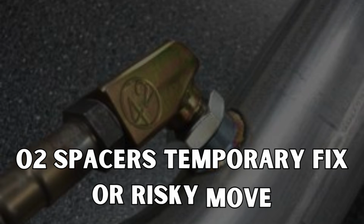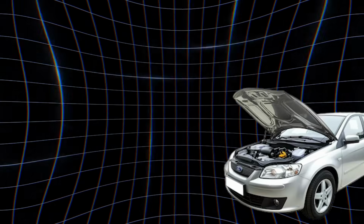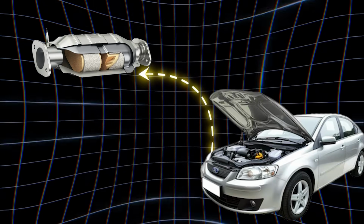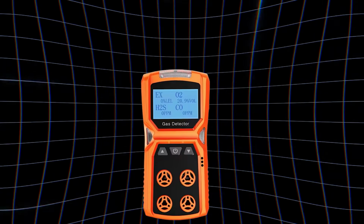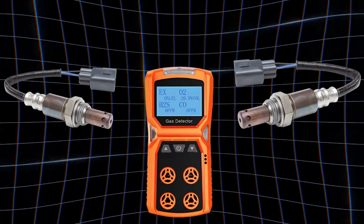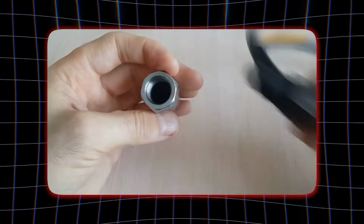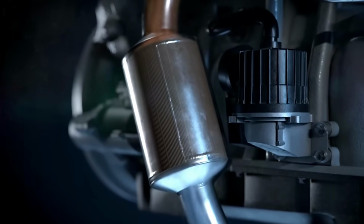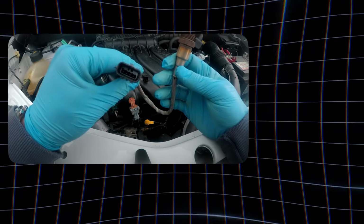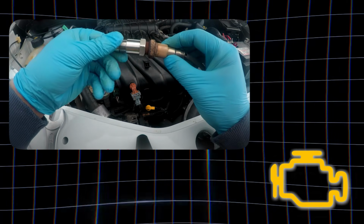O2 spacers, temporary fix or risky move. O2 spacers, also known as oxygen sensor spacers, are devices designed to temporarily mask issues related to a faulty catalytic converter by altering the readings from the oxygen sensors. These spacers create a small gap between the sensor and the exhaust flow, which can trick the vehicle's computer into believing the catalytic converter is functioning properly. This may temporarily clear a check engine light associated with the P0420 code.